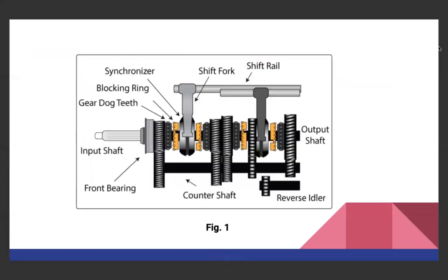So this is a schematic representation of the synchromesh gearbox which we have gotten from the internet. We can see a very similar construction to the constant mesh gearbox: we have the input shaft, the lay shaft and the output shaft. And in the gears, as we can notice, these are not the normal rectangular helical gears, but we can see conical protrusions as well. We can see the difference in the next slide.